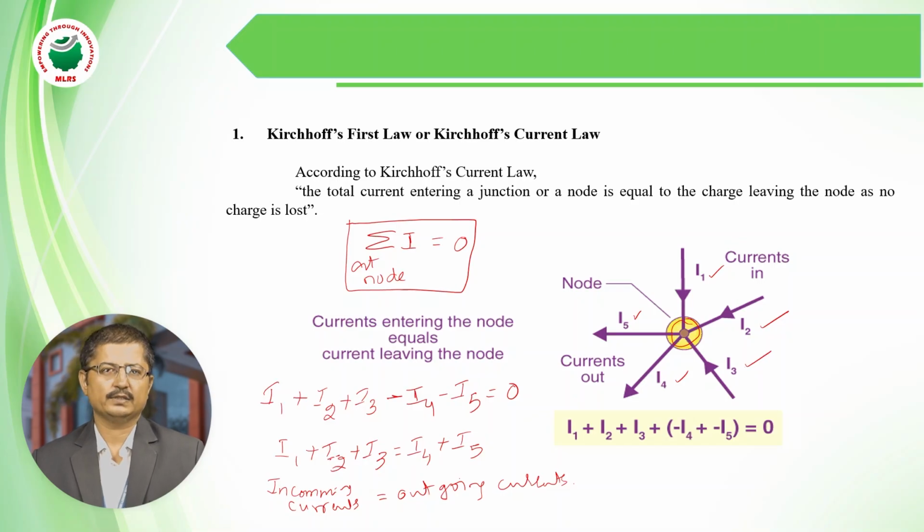In parallel circuits the current will be different, the voltage will be the same. We will discuss that in the coming classes: how the voltage is divided in series circuits and how the current is divided in parallel circuits, that is, the voltage division rule and the current division rule. So this KCL, the Kirchhoff current law, is used only in parallel circuits.